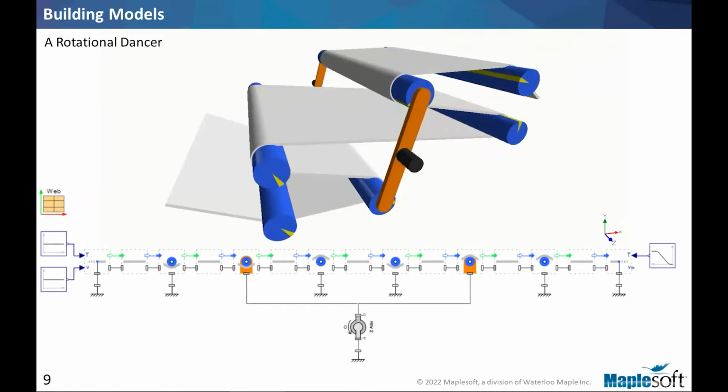We will review some of that, but the basic things that you would imagine for interaction of web and rollers are captured, such as inertia, diameters, inner diameter, friction, things like that. So they're all parameters that you can access and specify to capture your roll-to-roll process.